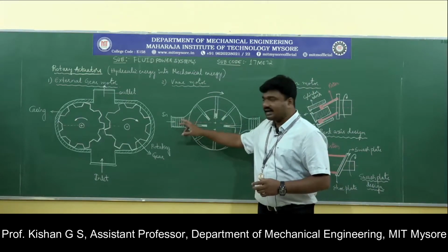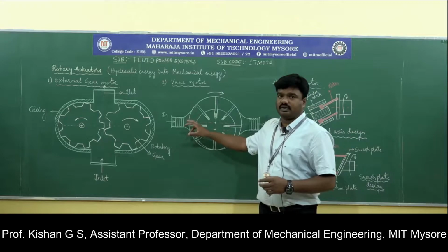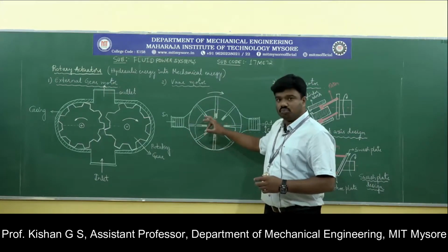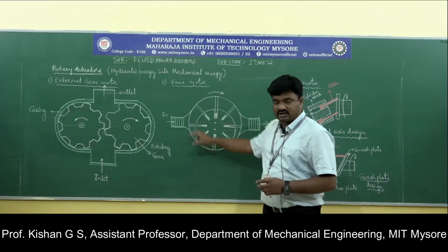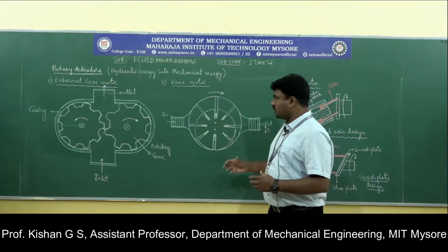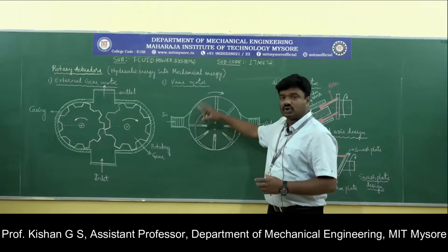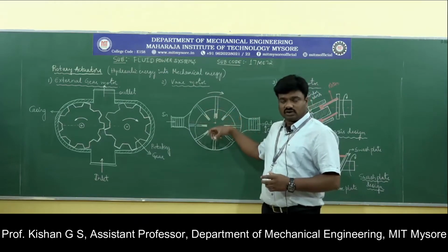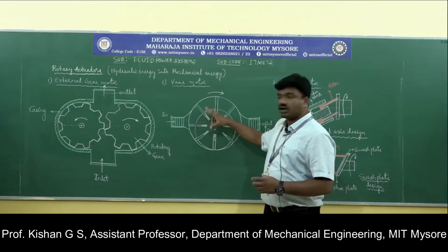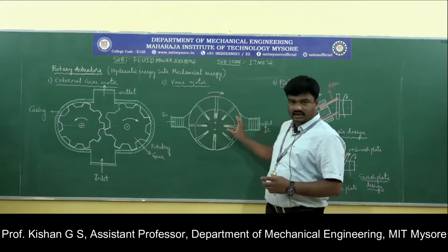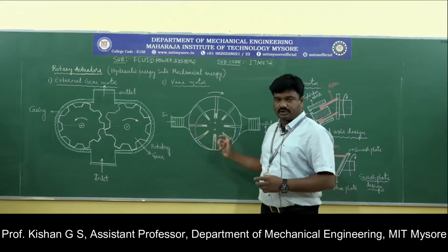Through the inlet, highly pressurized fluid enters the system and tends to move the vanes present inside the assembly. These vanes sit in slots in the rotor, and due to the movement of the vanes, the rotor tends to rotate in the clockwise direction as per the constructional principle.